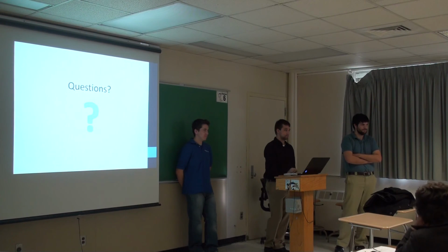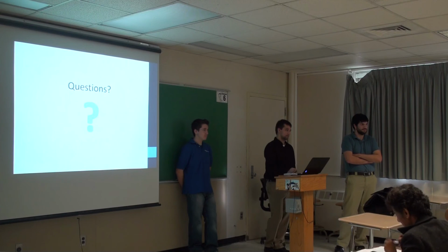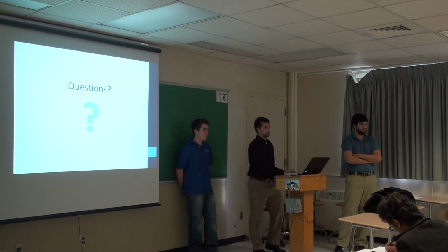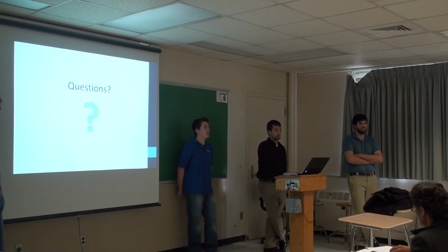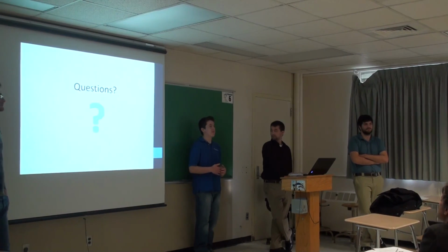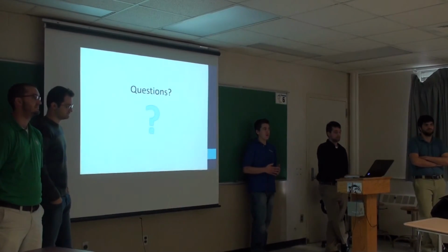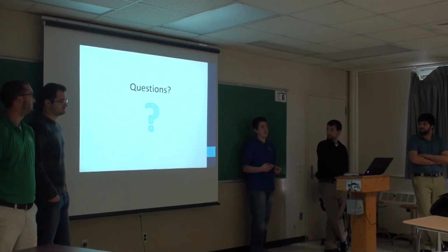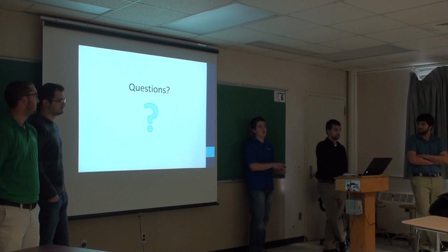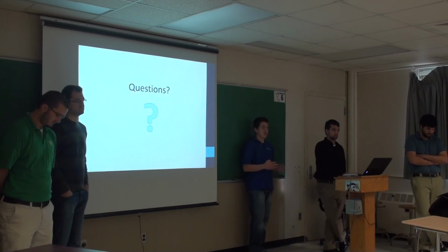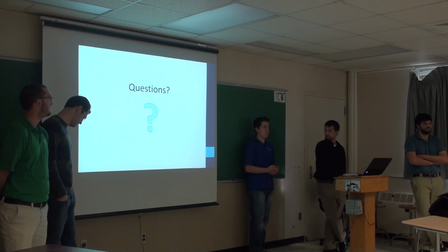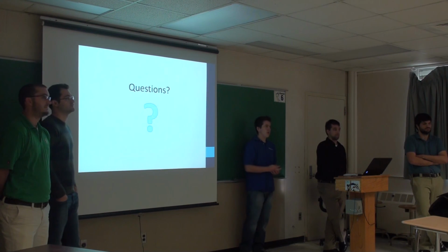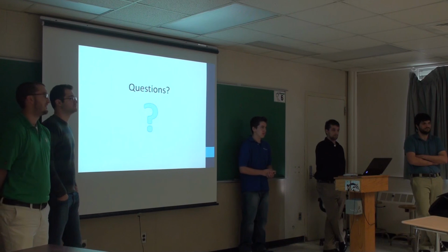Do you guys have any challenges with potential RF interference with your particular project? For our project, we're not really going to have any issue with the Bluetooth communication, because one thing that is an issue with Bluetooth is it does have a fairly limited range. But for our application, the phone that's controlling our RC car is going to be directly on the car itself. So it's not going to have any issue with signal strength, and it'll be the strongest signal being received by our Bluetooth receiver on our board. So we shouldn't have an issue really with any interference.